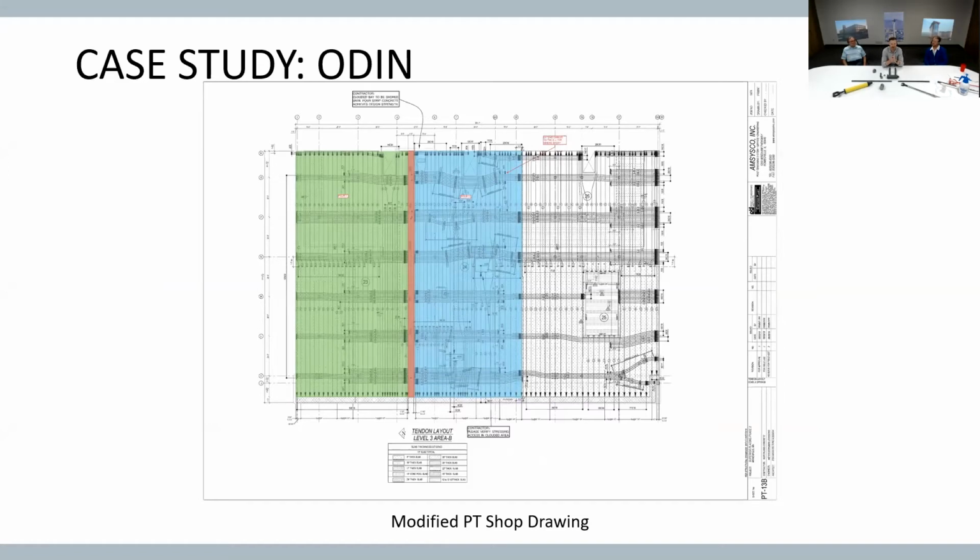So if it's a 4 foot wide gap, we like to close it 2 foot and 2 foot and just extend the PT a little bit through there. Because then that keeps the slabs basically, there's really no additional PT that the engineer really needs. Here, because of the construction sequence and where everything was going, we couldn't do anything on the green side, but on the blue side, we were able to make those PT cables longer and close the gap.